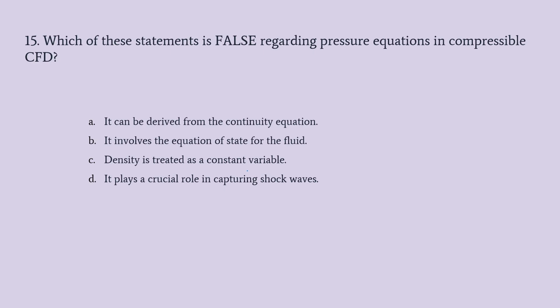Next question. Which of these statements is false regarding pressure equation in incompressible CFD? Option A, it can be derived from the continuity equation. Option B, it involves the equation of state for the fluid. Option C, density is treated as constant variable. Option D, it plays a crucial role in capturing shock waves. Again, a simple question. Try to answer the question.